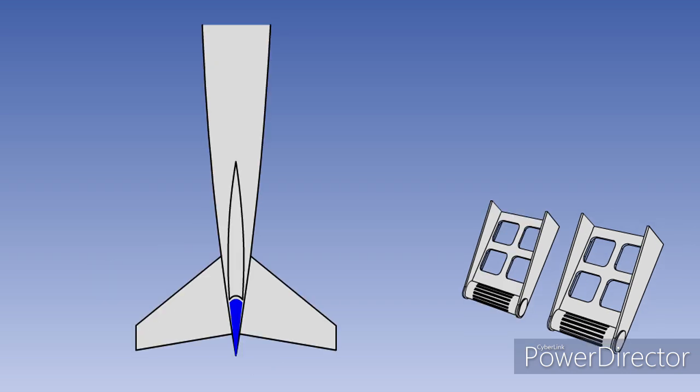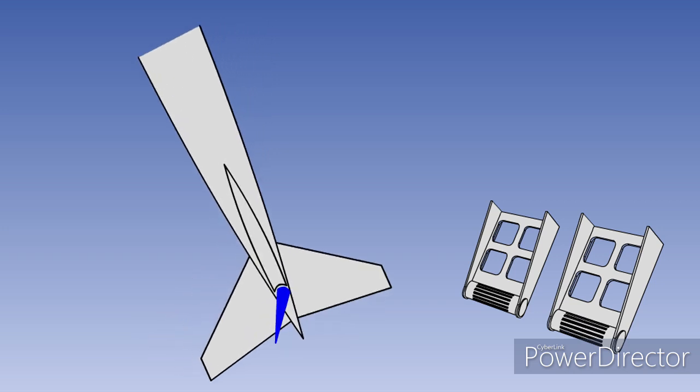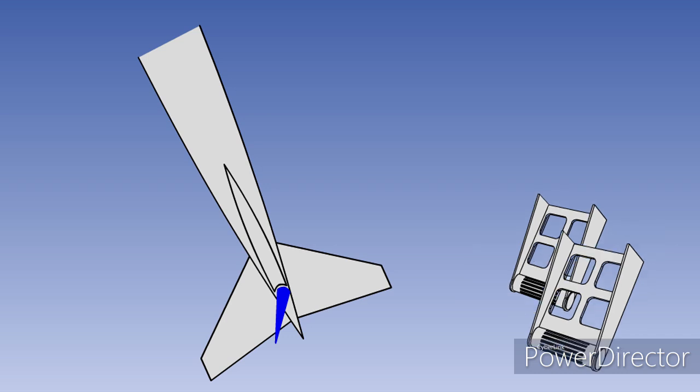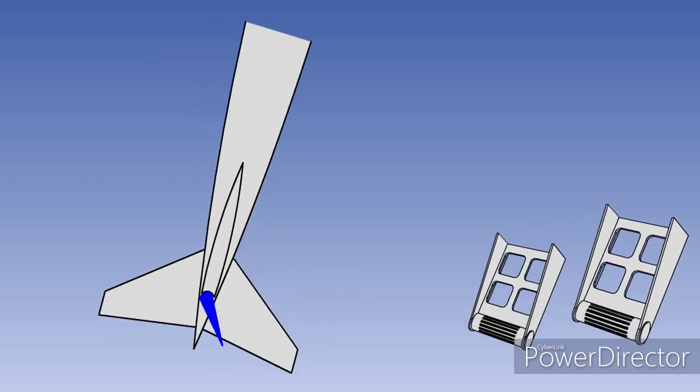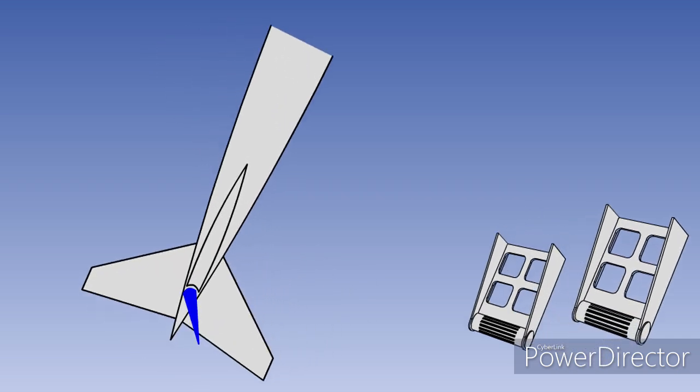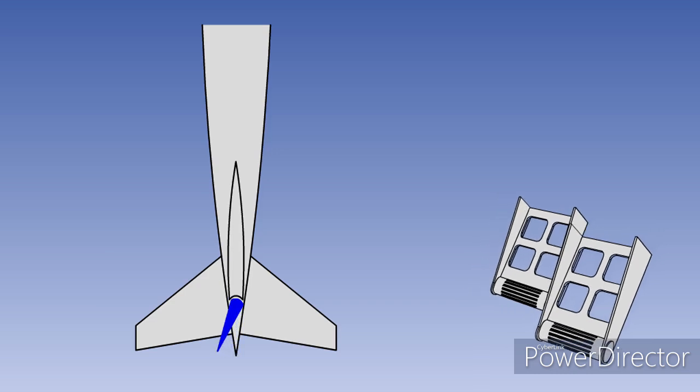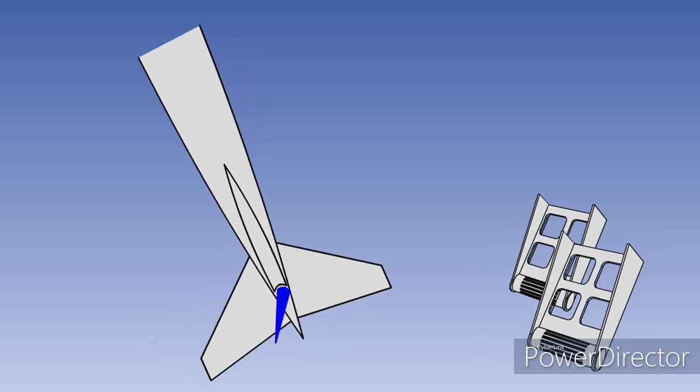The rudder is a flap-type control and is controlled from the cockpit by the pilot's feet moving the rudder pedals. Pushing forward on the right rudder pedal moves the rudder to the right, generating an aerodynamic force, causing the nose of the aircraft to yaw to the right. Pushing on the left pedal causes the opposite to happen, and the nose of the aircraft will yaw to the left.